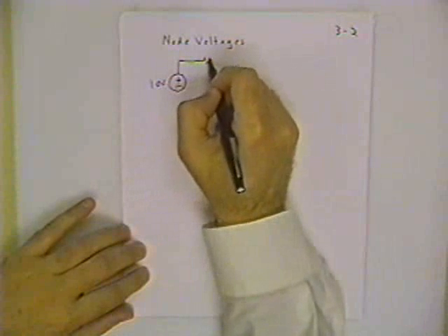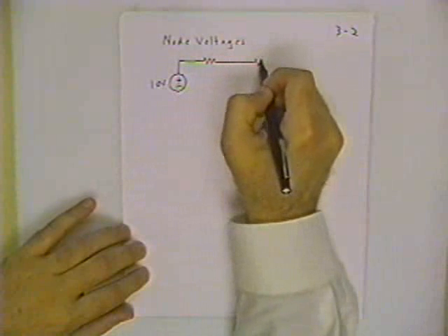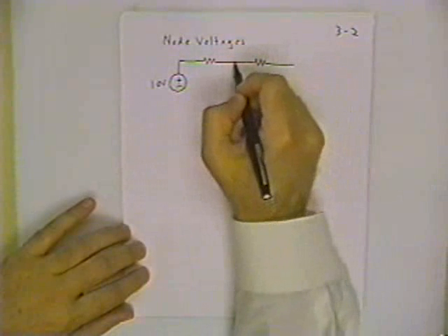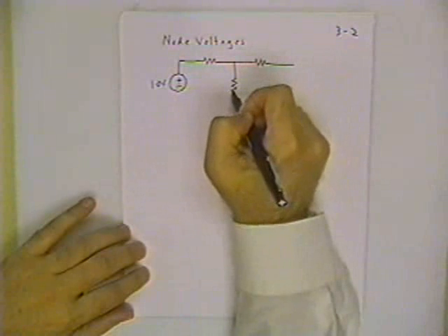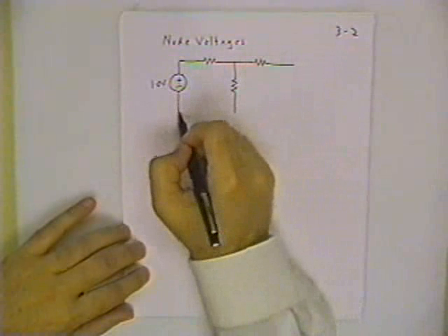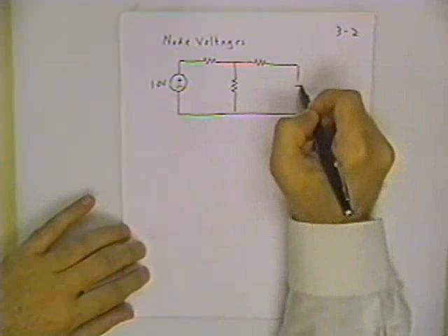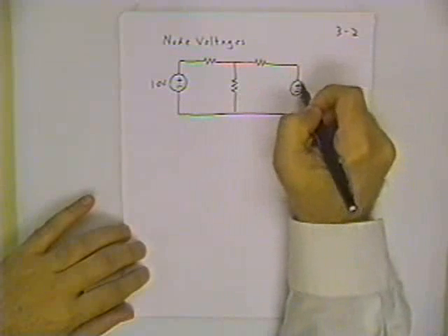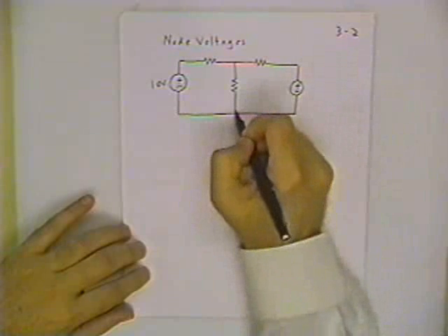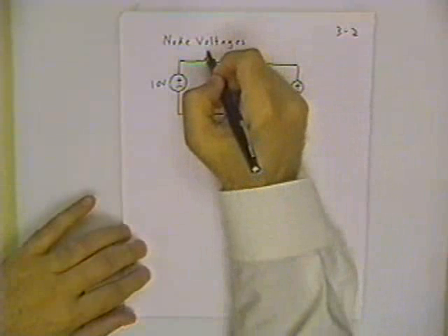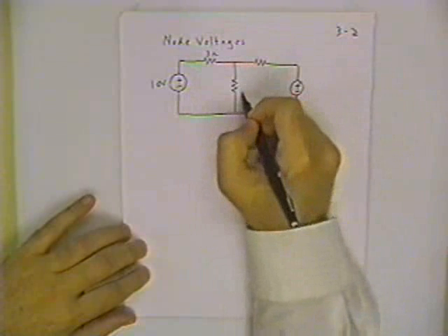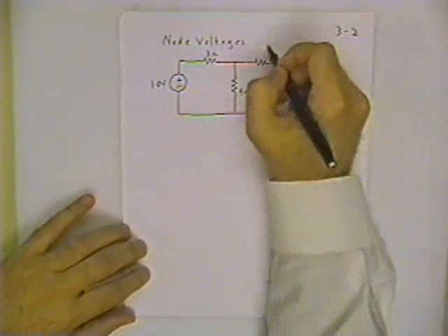One thing that should be pretty clear is regardless of the solution technique you use, you should get the same answers. When you have the luxury of a lot of time, that's really the way to figure out if you've got a circuit solved completely and correctly: check out all the Kirchhoff laws, and then once you've finished with one technique, you go ahead and solve the circuit again with another technique, and make sure you get the same answer.